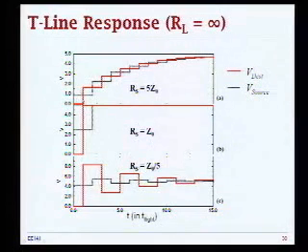In the plots, red is the destination, and the dotted dark line is the source voltage. What happens in this case that we just started analyzing is that over time, due to these reflections, you will have to wait a certain amount of time for your source and destination to fully establish at the final value.